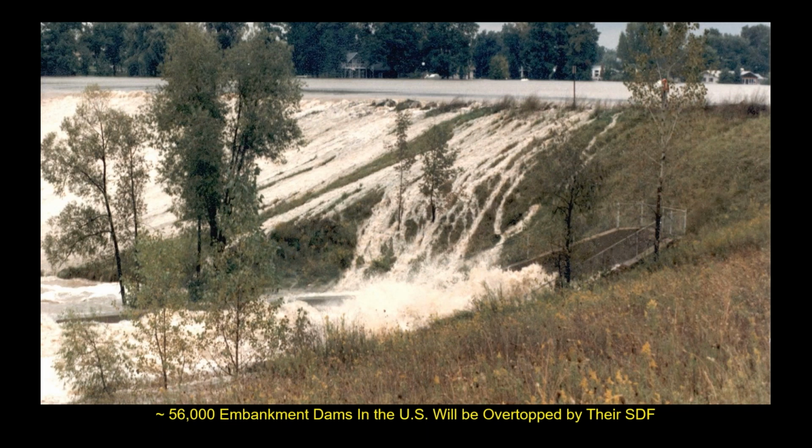And if the crest of the embankment isn't level, it will concentrate where the embankment is at its lowest. Oftentimes, these embankment dams are built with a camber. In other words, the main section of the dam is overplaced, it's placed higher than the rest, to account for any settlement that might occur. But most of the dams are so well built that they don't settle very much, and then the concentration will be at the groin or at the abutments of the dam.